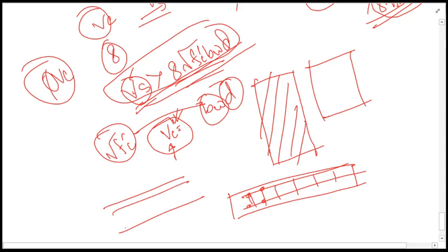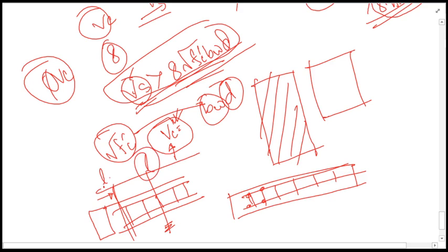So for example, you'll have to provide this shear reinforcement like this for the longitudinal section, and also you will be taking one section over there. If it is the support, at a sufficient distance, but not close to the mid section. You will be taking one section, say at a distance, if the total length of the beam is L, L by 4 from the face of the support approximately.